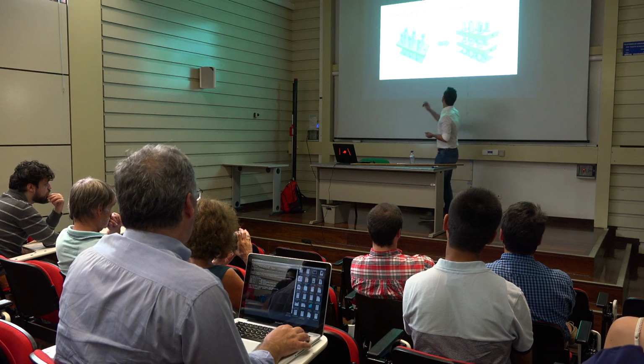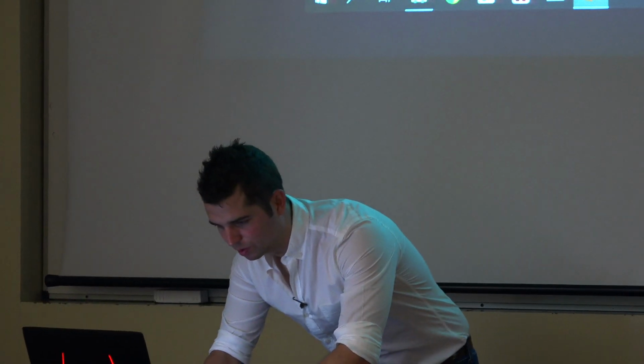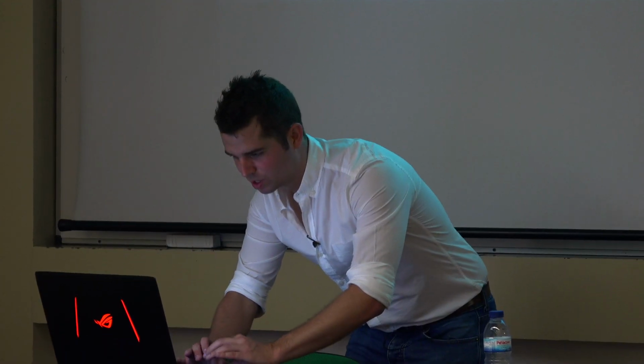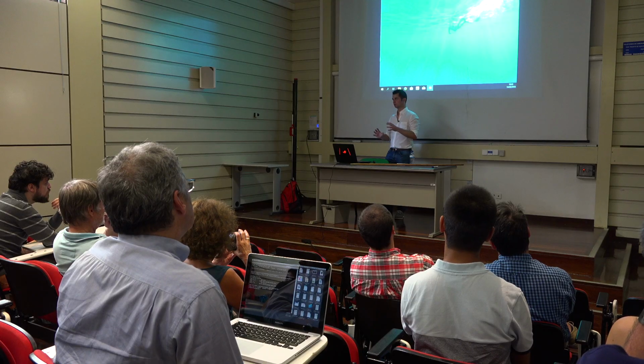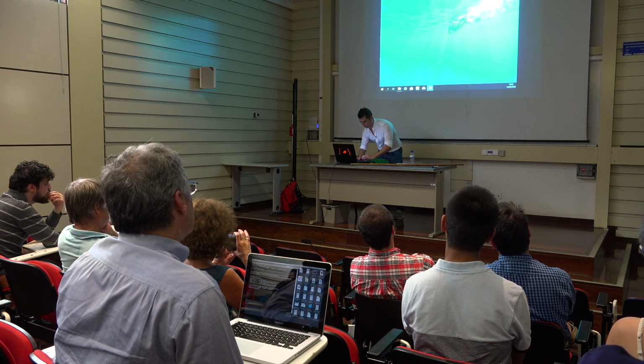I understand your question, but you don't only see these, for instance, on stacked transistors. The FinFET itself has already very complex parasitics. Let me just give you a simple example for you to think about it, because the parasitics are all related to the layout itself, so the way that the transistor comes physically, how it looks like.